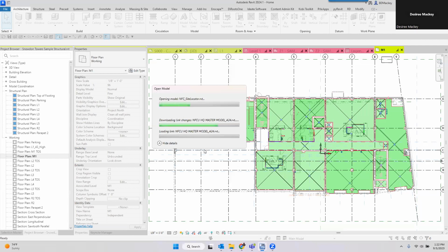Since I can't publish coordinates if it's on ACC or BIM 360, what I do is I literally just trace a couple of grid lines, grid line 1 and grid line A, in my site locator, but I call it the SL, or building A, grid 1, building A, grid A, whatever it's going to be, just so I can differentiate. These are my site locator grids, and I only do 2 grids. I do one and the other. I already have a level. Now I have those grids.